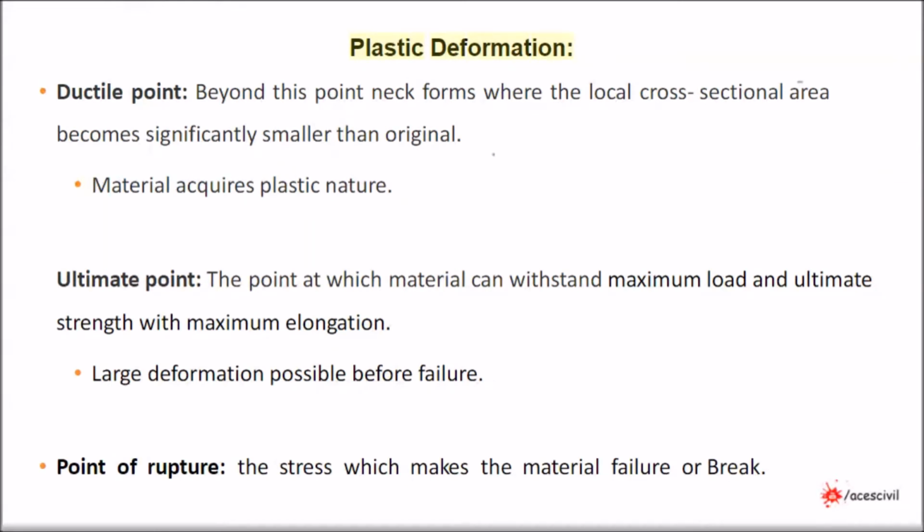Plastic deformation. Ductile point: beyond this point, a neck forms where the local cross-sectional area becomes significantly smaller than the original. Material acquires plastic nature.